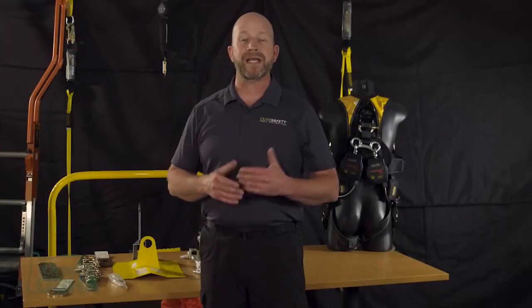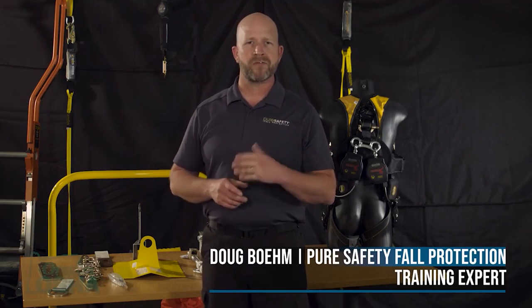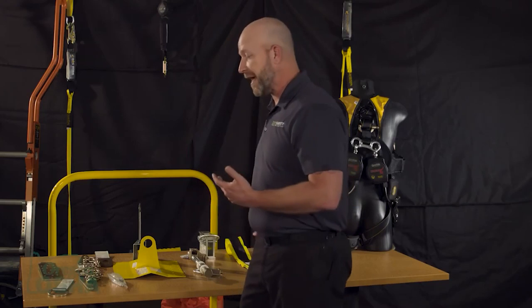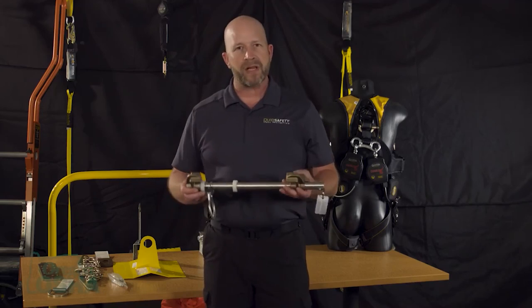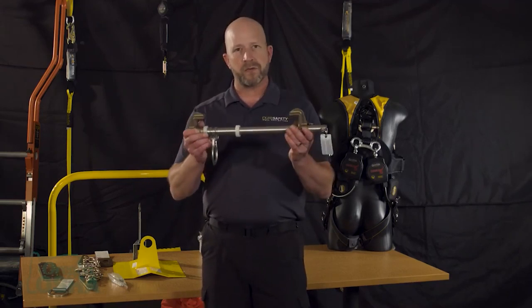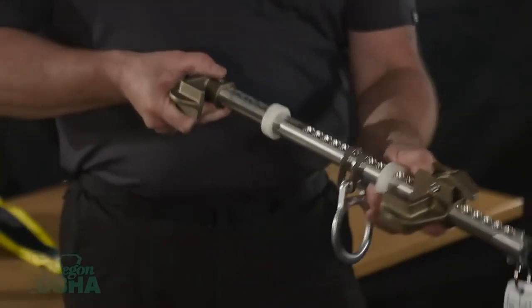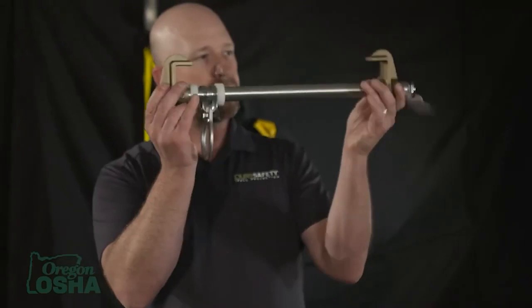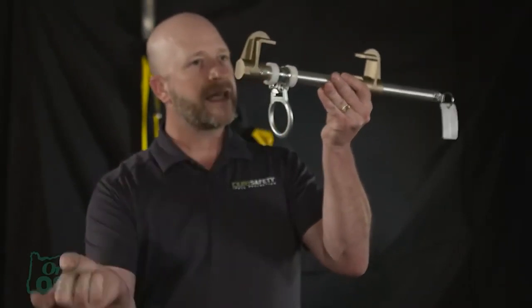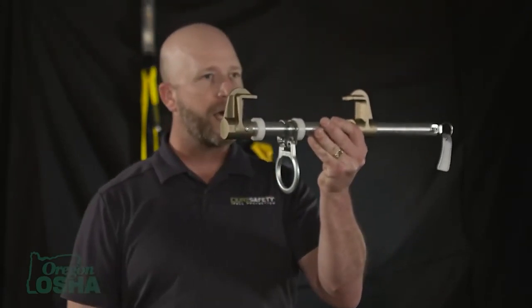There are many of us that work inside or in other environments where we don't have a walking surface such as a roof or a substrate such as that. Take an iron worker or something similar to that, where we have an exposed I-beam. Another common tool is a beam clamp that is designed to attach around multiple flanges merely by squeezing that trigger and getting it around one side of the I-beam flange, bringing it up like that, and then you will just slide it in, connect, and then we would hang our retractable or put our lanyard to that, and then it would be suspended from the I-beam.